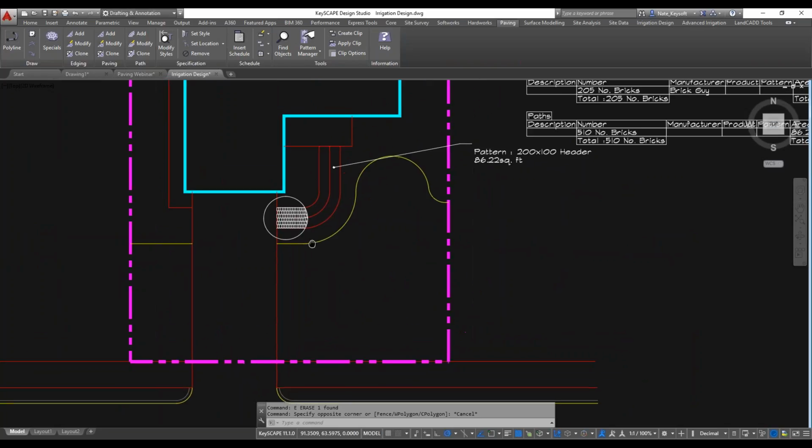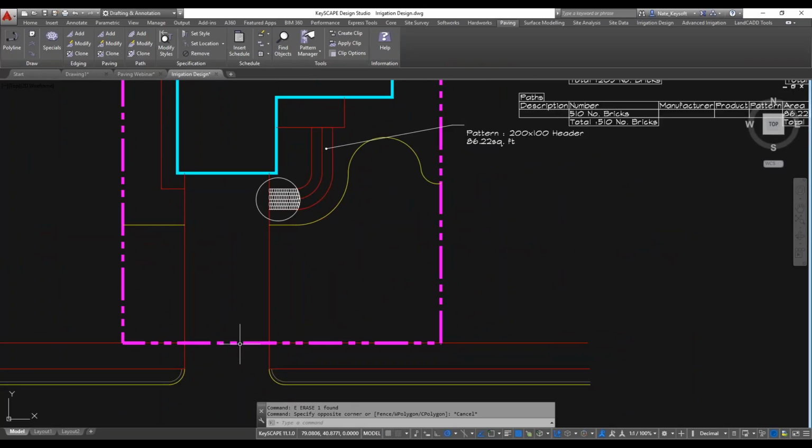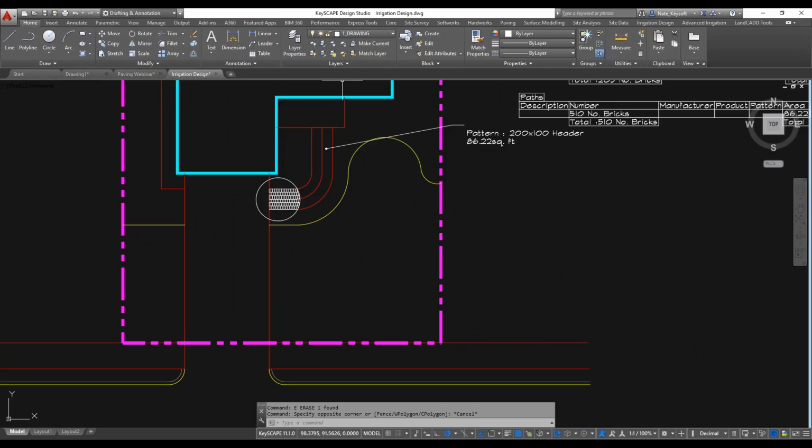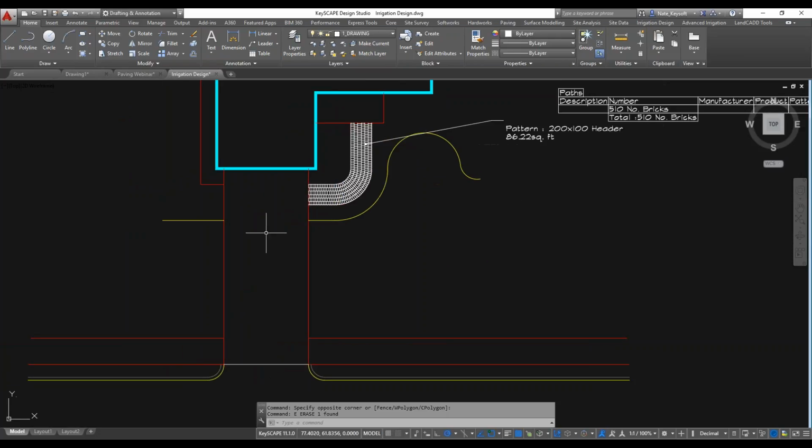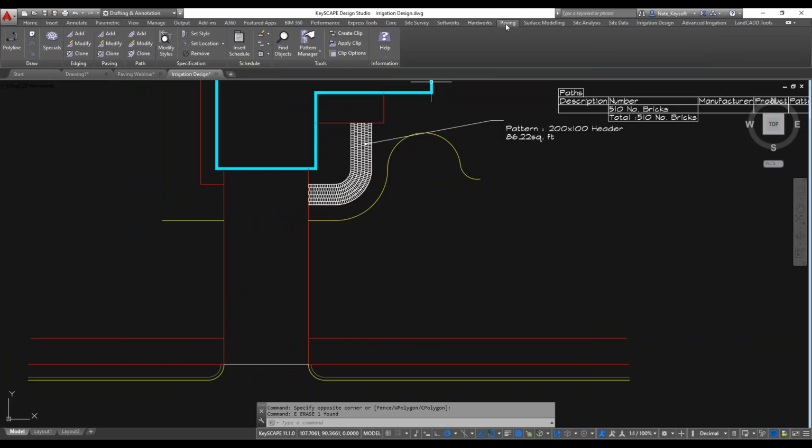And the last thing I want to do is, I kind of forgot about this. Let's go ahead and add a continuous surface just to demonstrate how you might use this tool to lay out or get takeoffs for just regular paved areas. We'll go ahead and get rid of that clipping area. So say I just want to say that, hey, this driveway is made of concrete. It's this many square feet. And I want to automatically create an item in the schedule for me so I can quantify that cost.